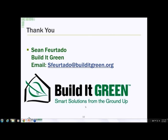I got a question for the alternatives tabs. What if I have two different types of windows? What you would typically do if you have multiple types of windows, let's say I have a slider in some situations and double hung windows in others, and the double hung window has lower performance than the sliders, is use the solar heat gain coefficients and U factors from the lowest performing window, not the highest performing window, and they're not averaged.